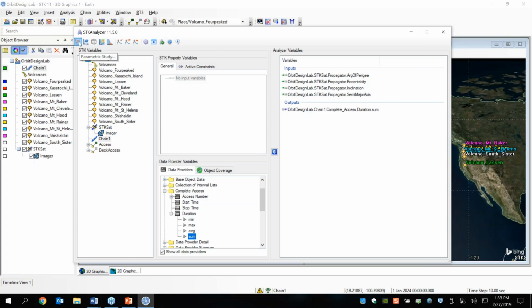So a parametric study is when you vary 1 parameter, see 1 result. Carpet plot, you vary 2, and then see your result. And then design of experiment, you can have X number of variables and X number of results. And then we also have optimization tools, probabilistic tools, and then you can see all of those if you just hover over the names over here. You can also script in various macros if you want to automate any of your analysis steps.